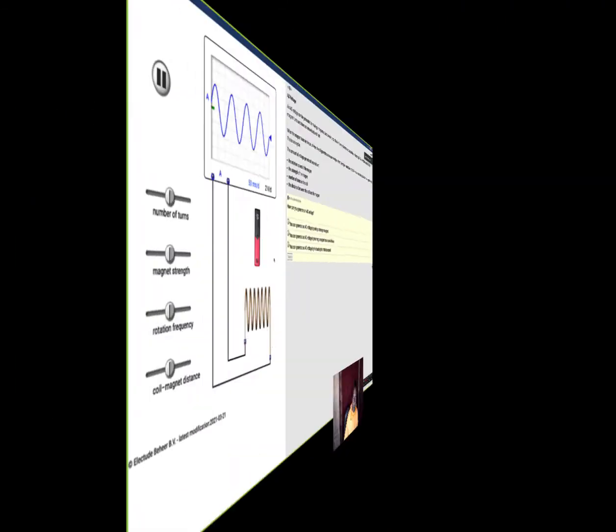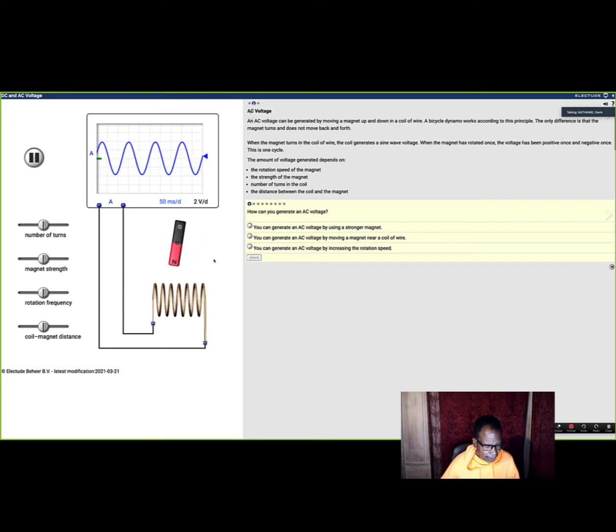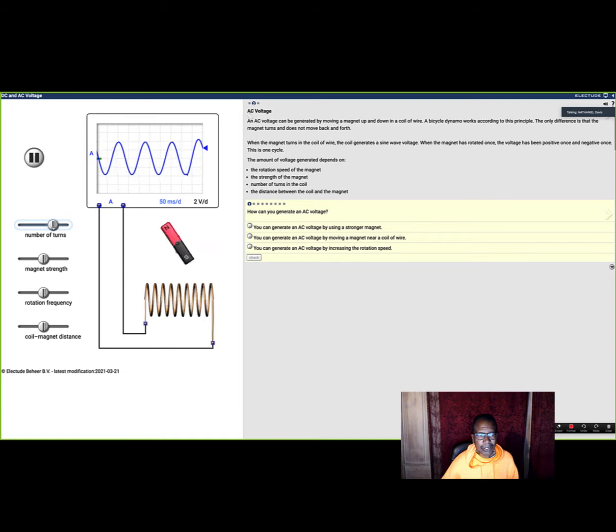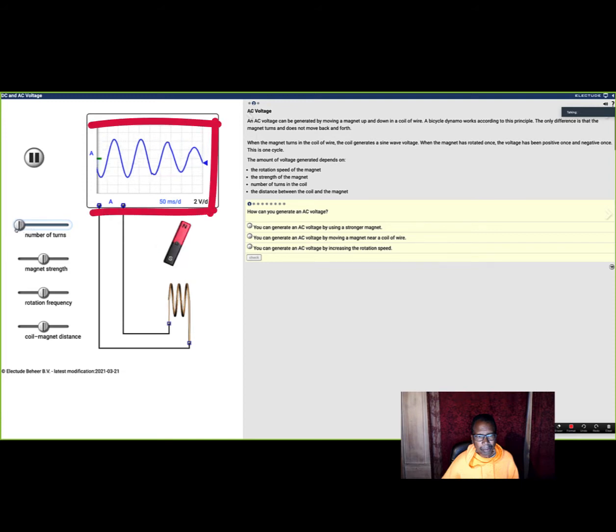Now let's think about you putting in a permanent magnet crank sensor, and the gap is too wide, or the magnet gets weak. If the coil itself is weak, the amplitude of the signal also gets weak. This is what this is telling you. Here, this is an increased number of turns. You see how big it got? Now let's say half the coil was weak or got shorted. Watch the signal. See how smaller it gets?